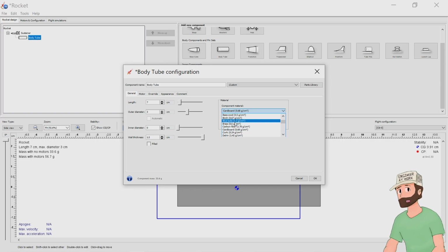Blue tube? No idea what that is. Cork. Cork is a really good rocket material. I have cork in a bunch of stuff. Cork is great for fire stuff. It does not burn. Well, it does. It just burns incredibly slow. I think I'm going to be doing it out of PLA, so 1 second. What's the approximate density of PLA? About 1.25 grams per cubic centimeter. Custom. Oh. PLA 1.25. That's if we're doing solid. Add material to database. Boom.